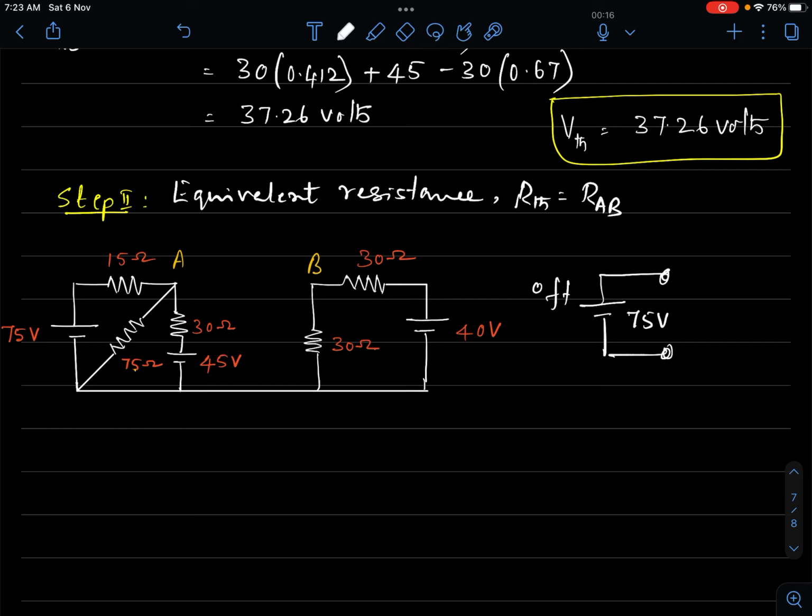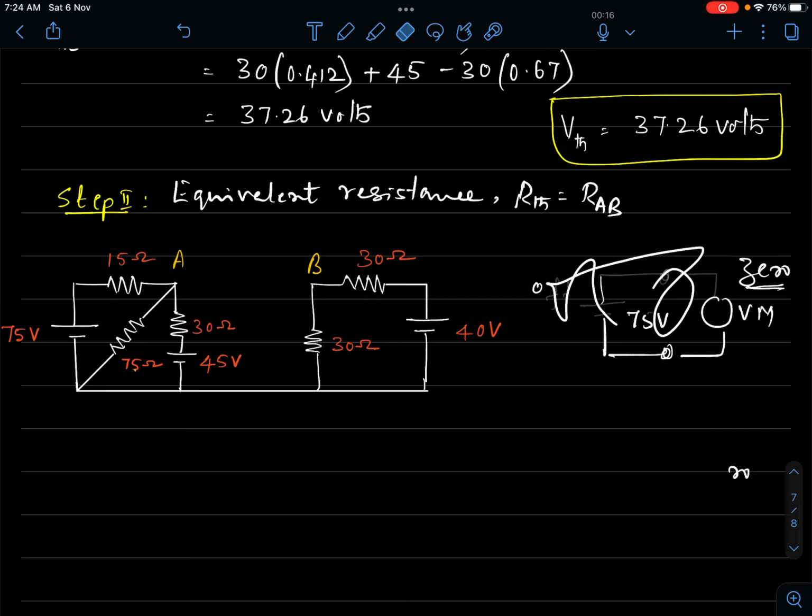even if we connect a voltmeter here, it will record 0 volts. So if we switch it off, you record a 0. That means the switching off condition should give 0 volts. So the switched off condition obviously would mean a short circuit, because across a short, if I connect a voltmeter, what do I measure? I'll measure 0 volts. So hence the switching off condition of a voltage source is represented by a short circuit.